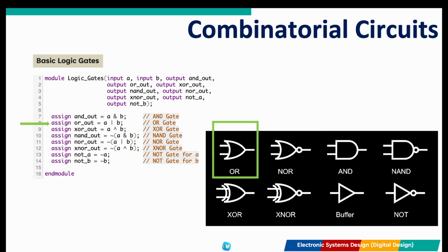Next, the OR gate. This represents a parallel path. The output Y is high if either A or B is high. We describe this with the OR primitive. The exclusive OR is unique. It only outputs a 1 when the inputs are different. The gate is the mathematical heart of arithmetic circuits like adders, which we will explore later in this module.